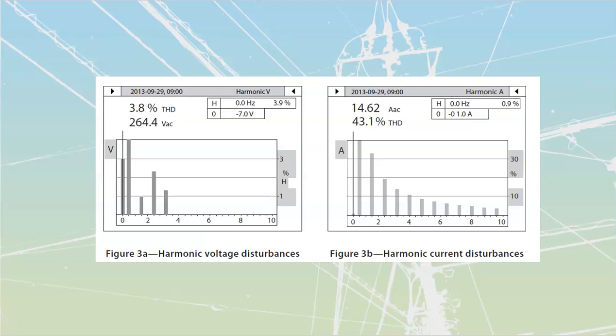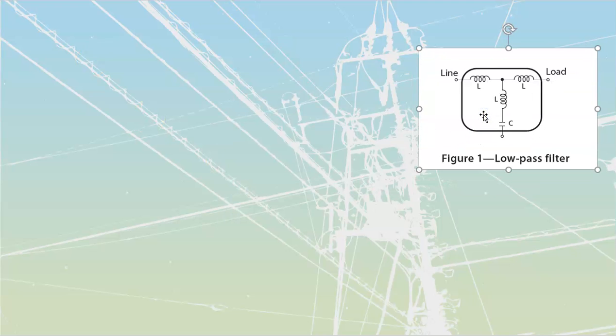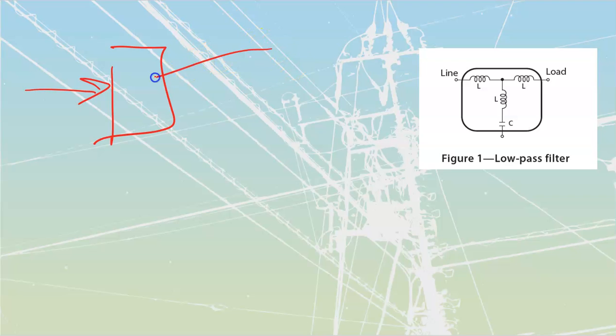If you are still having issues past the original installation, where you're oversizing and your pre-building didn't work, then you're going to take a look at power conditioners. Power conditioners are going to be placed at your main service, and in a lot of cases they are going to try to snub anything before it either gets in from the outside or before we send anything back out to the outside.